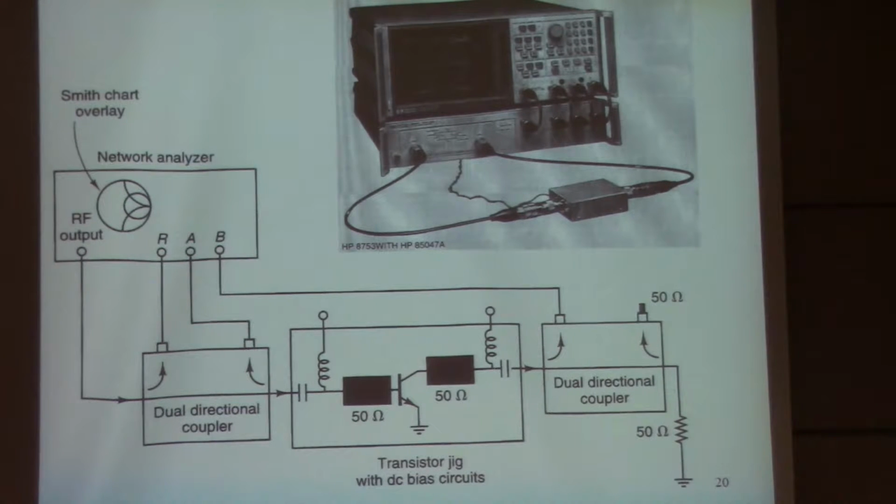and at the same time you can measure the high frequency behavior of your transistor. So today, actually all the high frequency properties of transistors are obtained with this technique, this measurement. And yeah, even the IV curves they give you at high frequency are converted from S parameters.